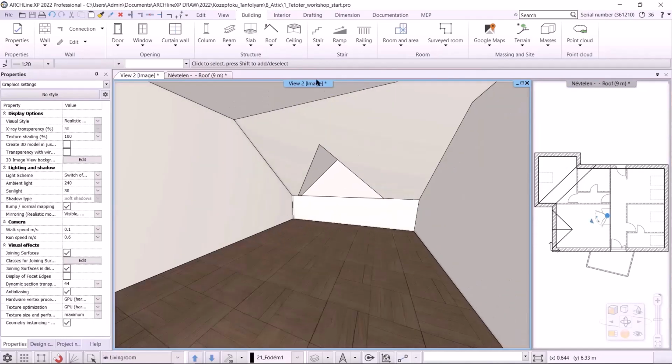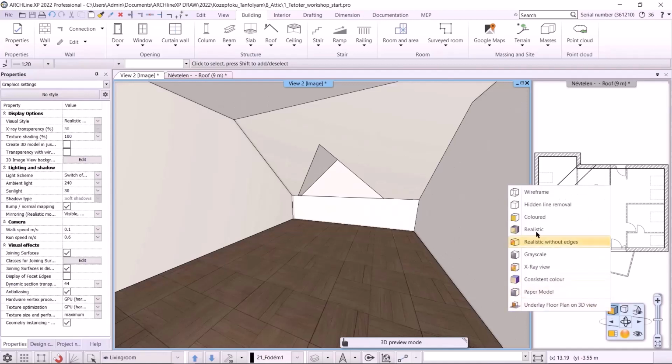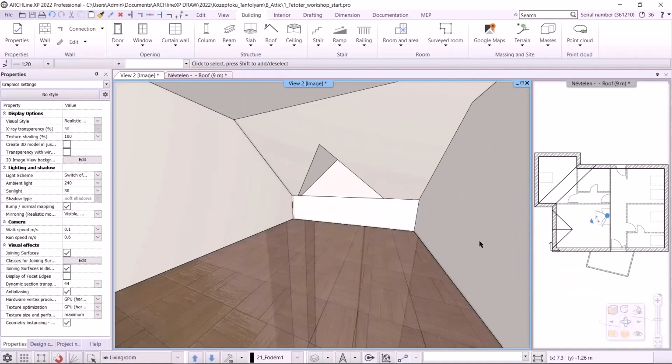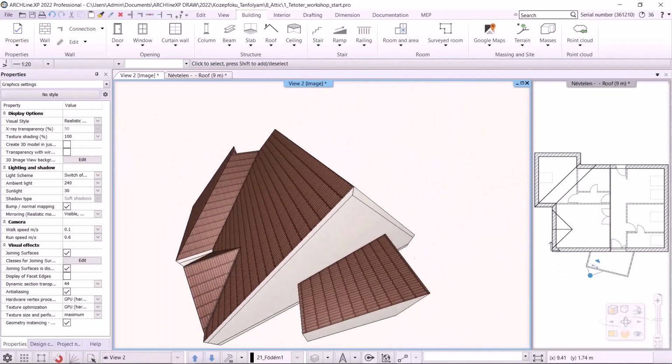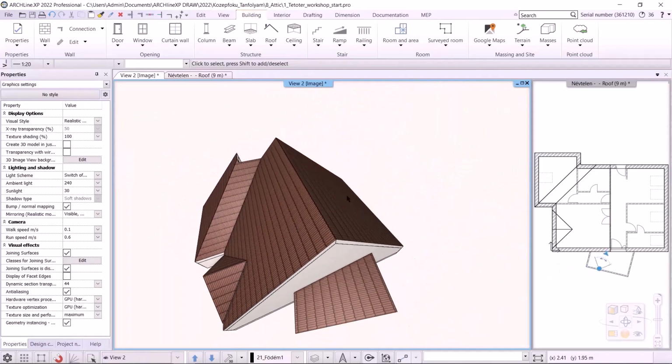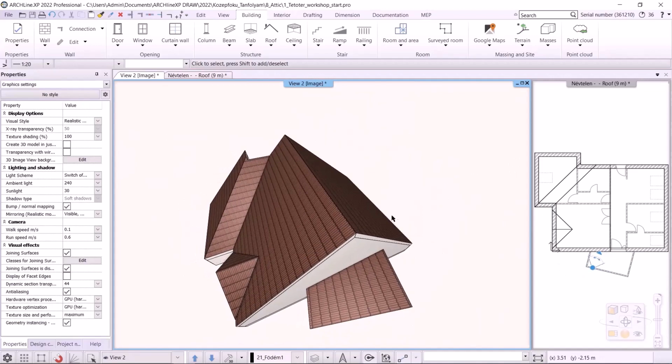This is what the roof, slab and wall connection look like. I switch to Realistic View. Now I'll place roof windows on this building. I select the external level. I activate the 3D window and rotate the model to make clearly visible the 2 roof plane.